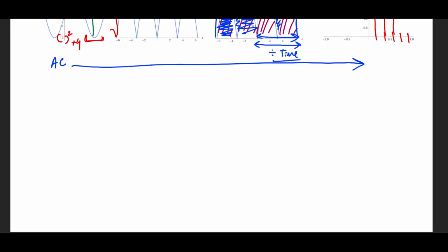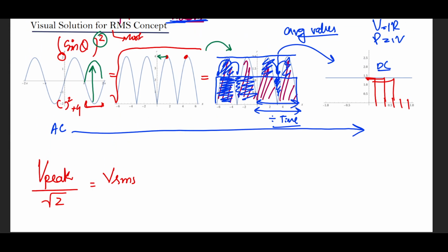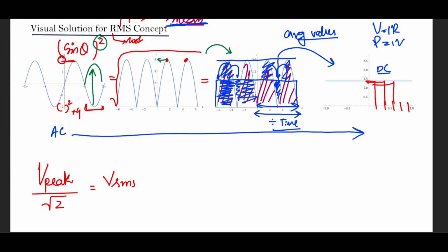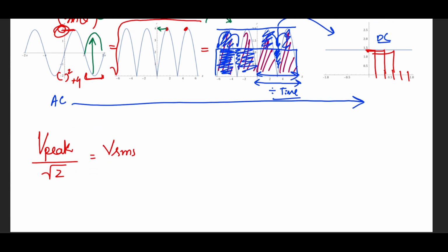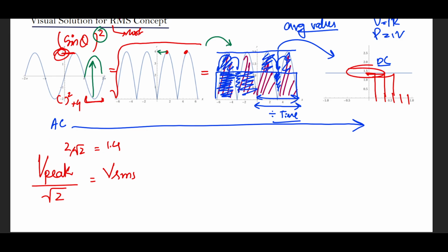Now, the formula for current and voltage is V peak voltage, if divided by under root 2, gives you an answer of voltage RMS. So what you do effectively is you choose the peak value. Let's say this was 2, for example, over here. So I put in 2 and then divide this by under root 2. This will give you an answer of 1.4, which is somewhere over here, which is where the line is stationary at this point. You can try this over again, right?